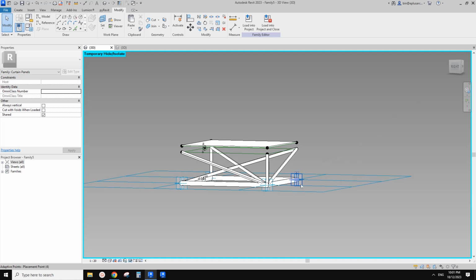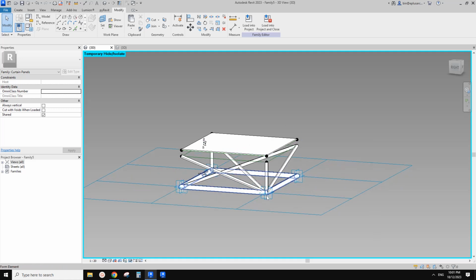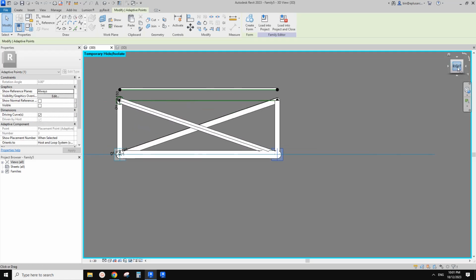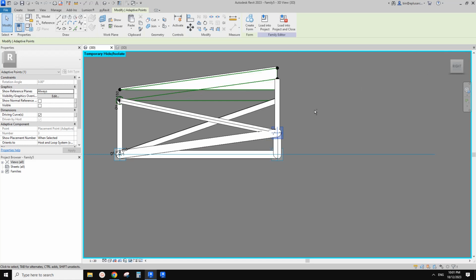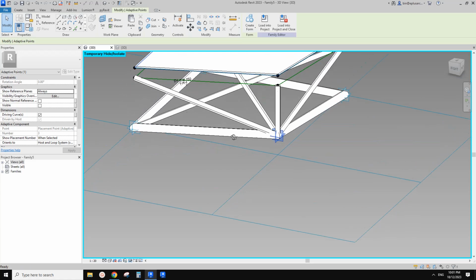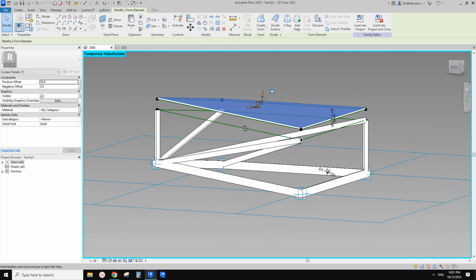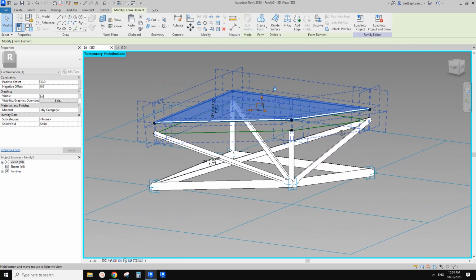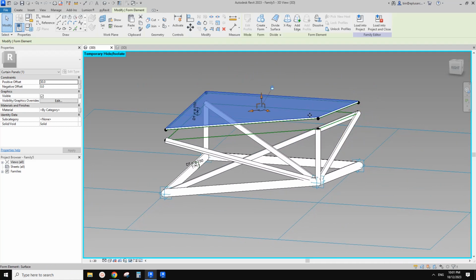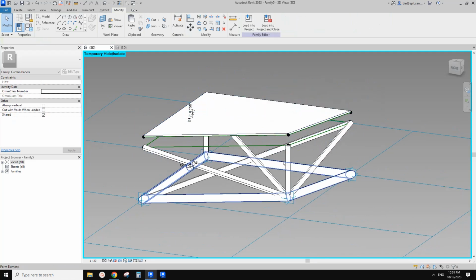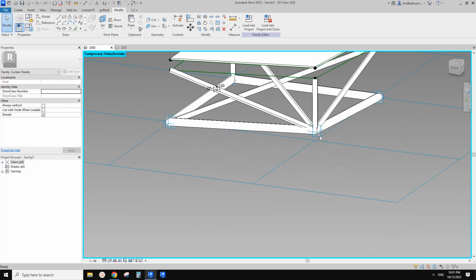You can try this: select one of the points, so 1, 2, 3, 4 point, any of the points, click on this side face, and use your keyboard to move it up. Okay, now let's have a look. You can see it's become a curve, but at least it didn't break, which means it will be fine. So we've tested this, it works. We can Control Z, go back.